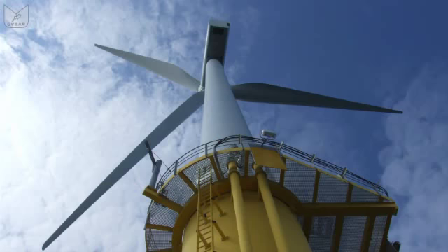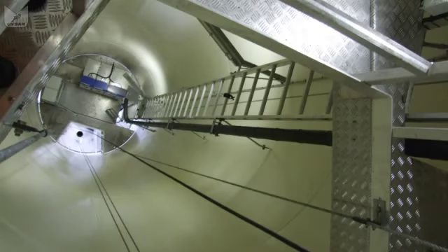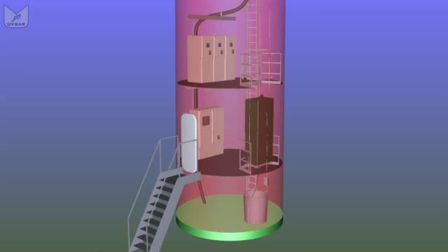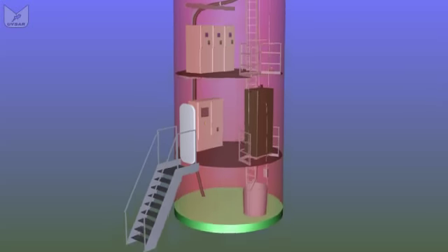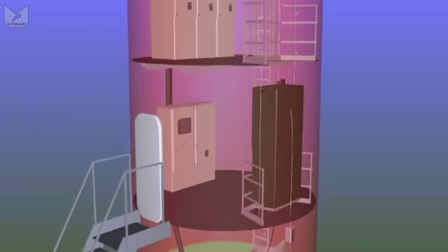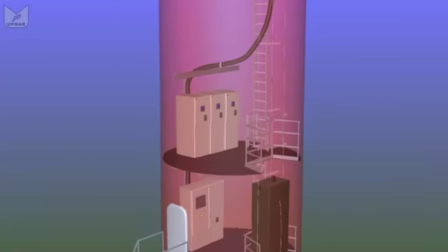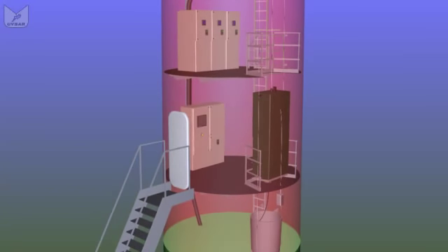Where we place the high voltage transformers in multi-megawatt turbines is a lot more variable. Quite frankly, we have a lot more room, so we can decide if they can be in the nacelle, they can be at the base of the tower, they can be on platform 1 in the basement, they can be outside in a hut. In this example, the transformer's at the top, so when we go into our door, the one thing we'll not find is a transformer. We do have the high voltage switches, in this case on platform 2, but on the entrance platform we have the usual control cabinet and a lift, a little green box.